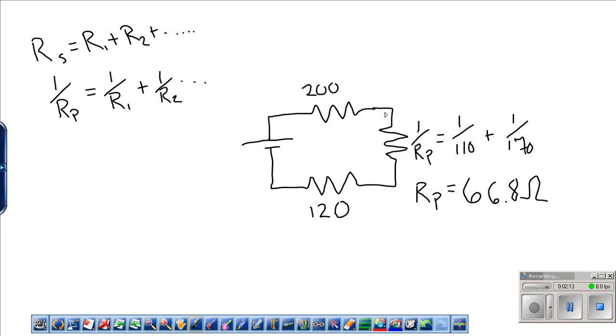So let's take that 31 milliamps, so 0.031 amps, and see what we can get using that and using our resistors here. Again, consider Ohm's law. V equals IR. There's only 3 terms in there. The beautiful thing is that if you know 2 things, then you can figure out another one.